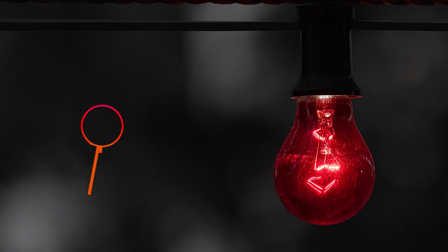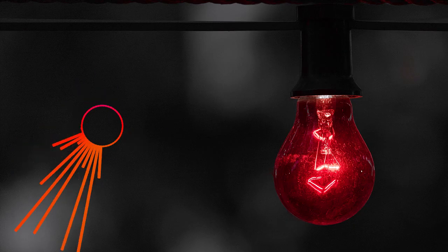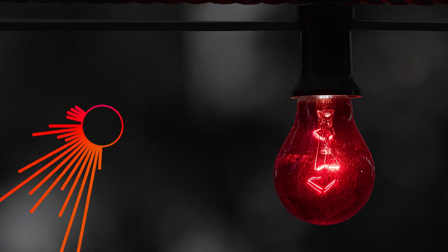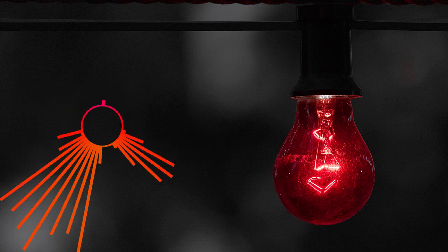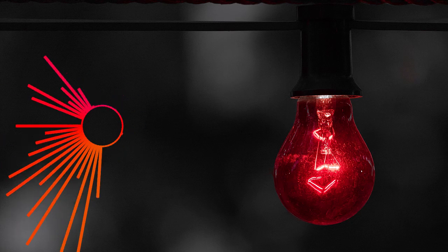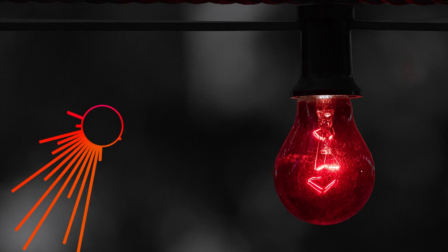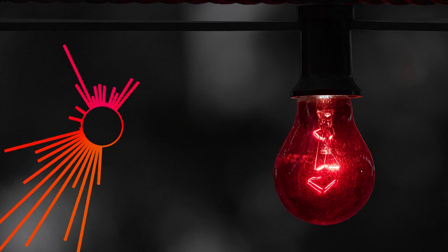And remember, each lighting system has many types of lamps, ballasts, and drivers within it. Your job is to know the basics and be ready to learn the details as you go. As an apprentice lighting technician, you'll be expected to identify what kind of lighting system you're working on, understand what components it needs, such as lamp, ballast, driver, and know how to replace or upgrade it safely.